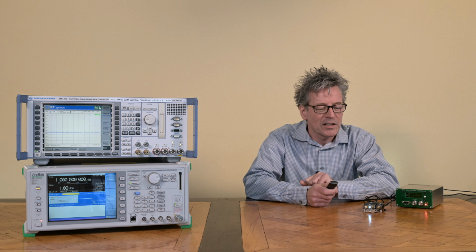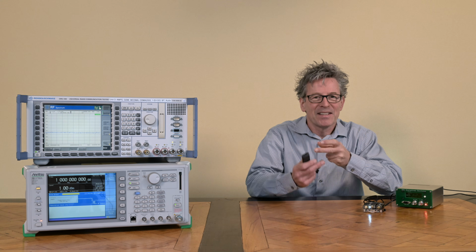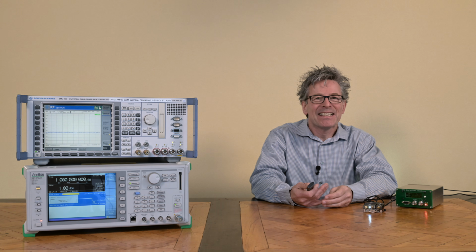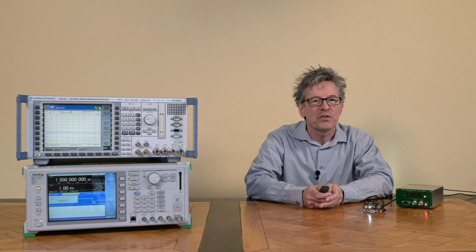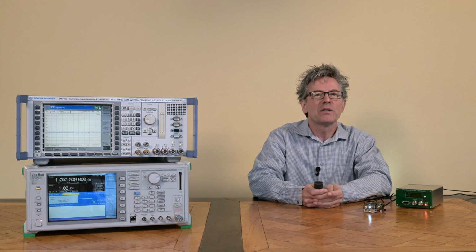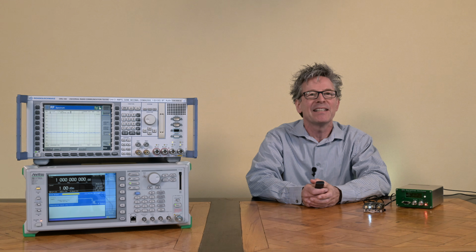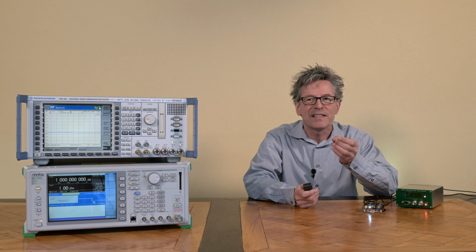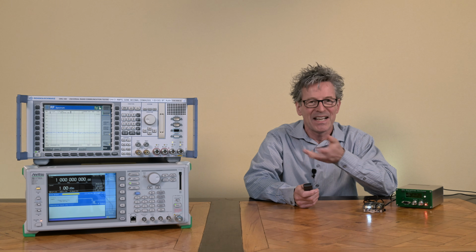Now, about the criticism of these people, I think the thing is that the Leo Bodnar unit can deliver any frequency, and to have that at the same time as a sine wave is kind of an unrealistic thing to have, because then you would have to build all this type of circuitry into it that you find in a very fancy and expensive signal generator to create any type of output without all these harmonics, etc. I think that's completely out of the context of a little device like this. So if you want its frequency to be selectable and not fixed at 10 megahertz, then I think you will have to live with the square wave thing.